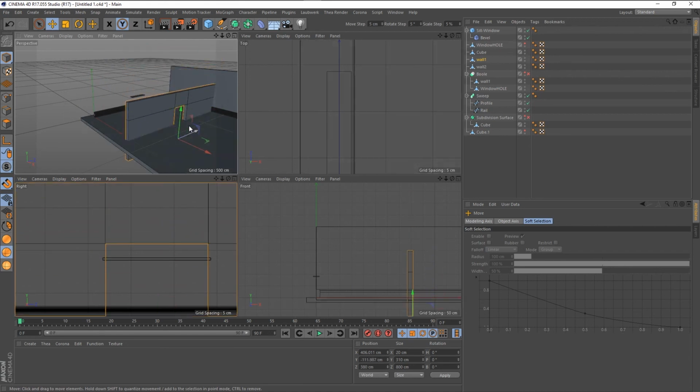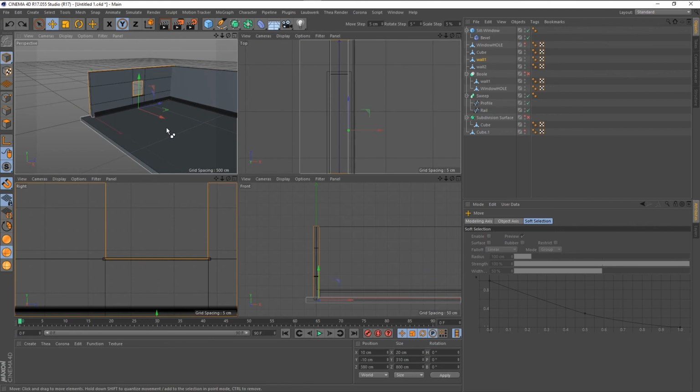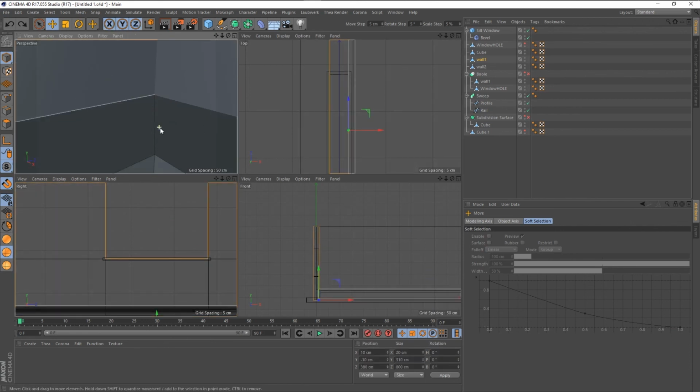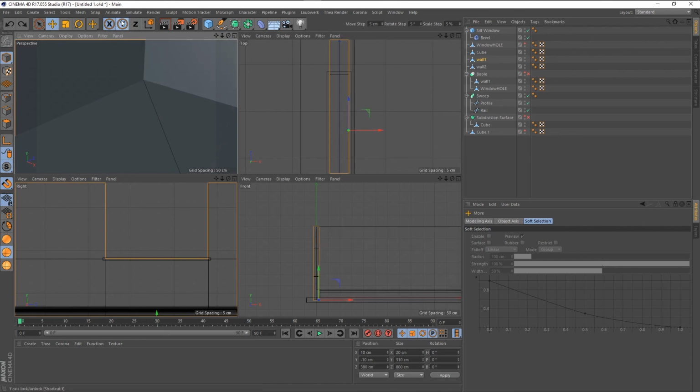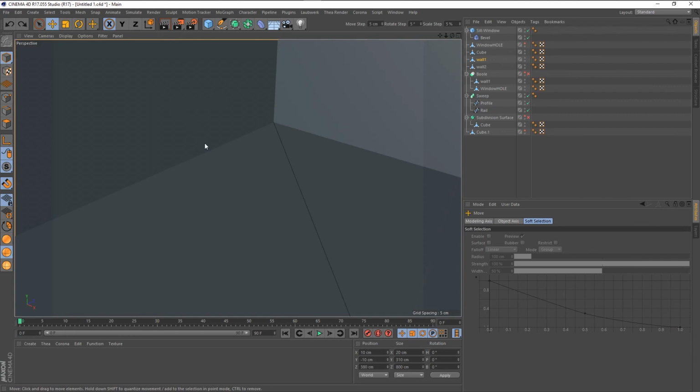Sometimes if you can't see the axis and you're zoomed in, let's say we zoom in real close here, and we can't see the axis. It's now outside of our view, and we wanted to quickly adjust. We just want to tweak the movement of this thing. I can disable Y and Z, and I can just click and drag here. Whoops. I got to turn off snaps. So Shift S to turn off snaps. I have quantizing off, and now I'm only going to be moving in the X.